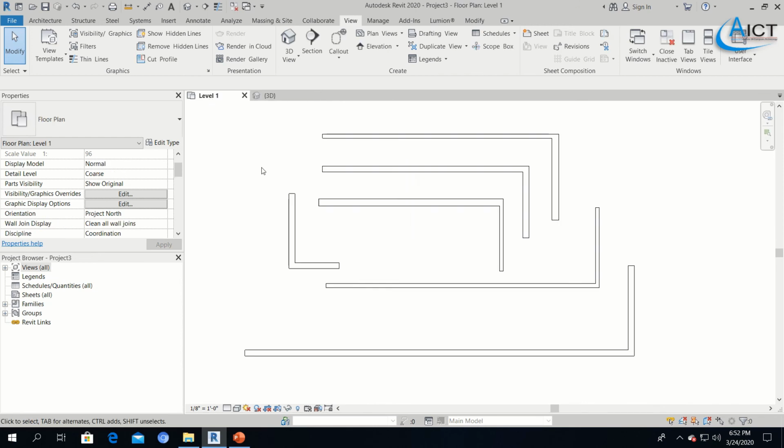Right. So in this lesson we have learned how to draw walls and how to create walls. It means how to change the width of the wall and the height of the wall. And so we'll finish this session and we will see you in lesson 2.